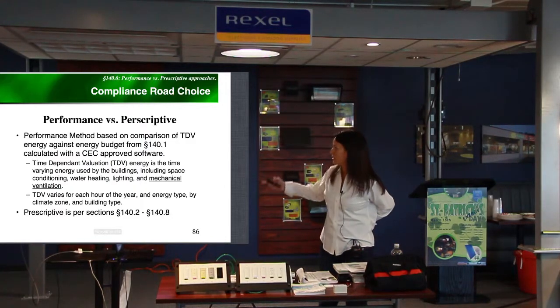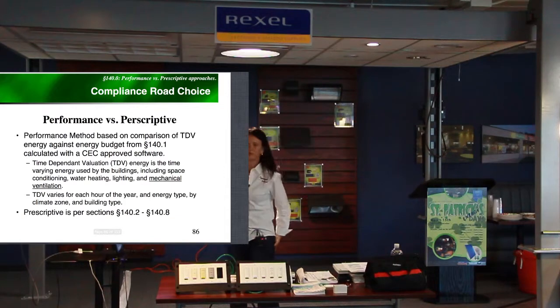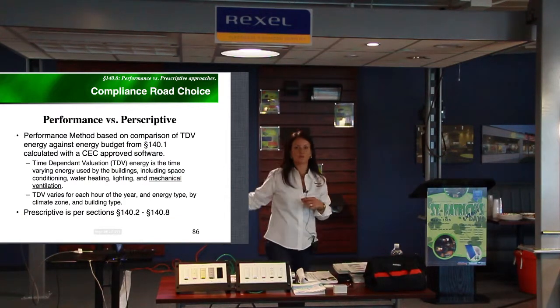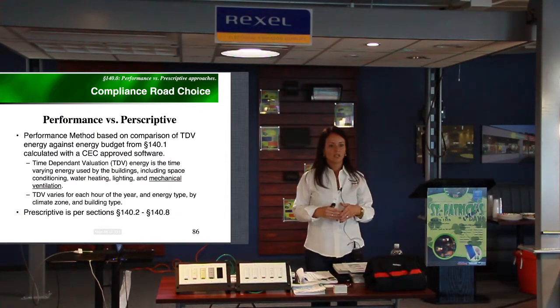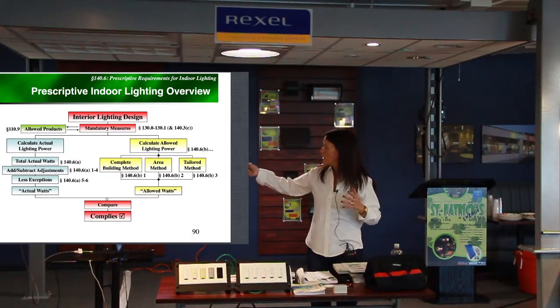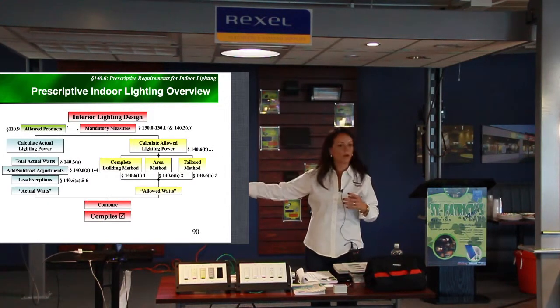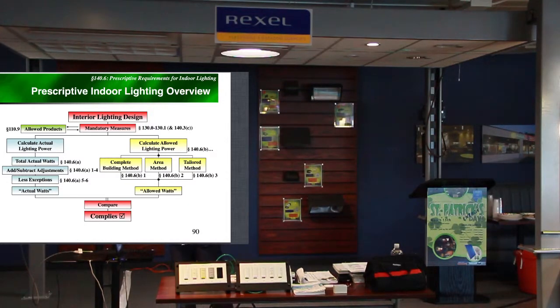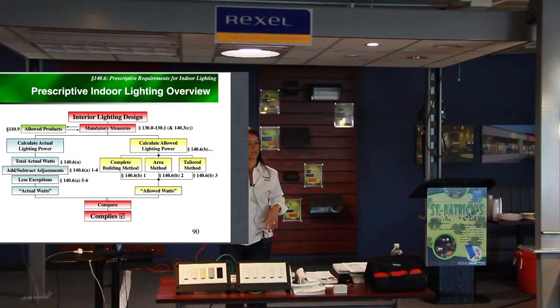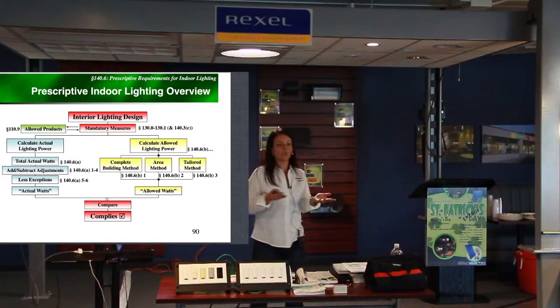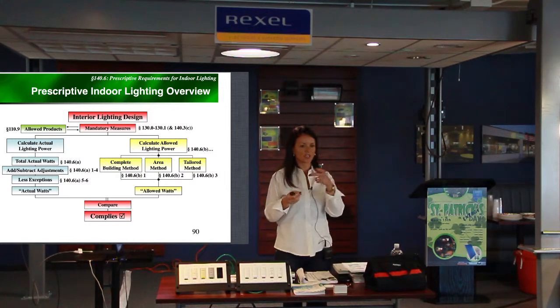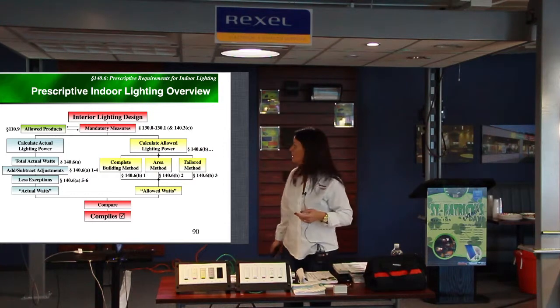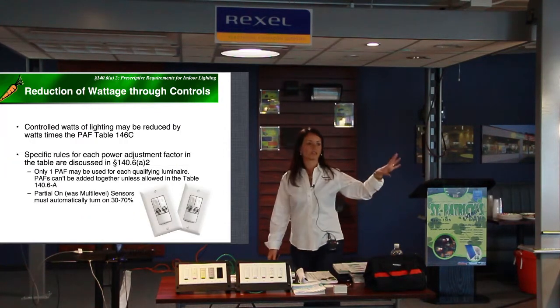Prescriptive methods, I think 85% again of the electrical engineers follow the prescriptive method, which means you check what's allowed, so your actual lighting power based on all the lighting power densities that you use, and then you check what you calculated and you see if it complies. So that's pretty much how most of the electrical engineers do, check, check, check. Design building contractors will do the same. In that case, remember the carrots that I talked about.